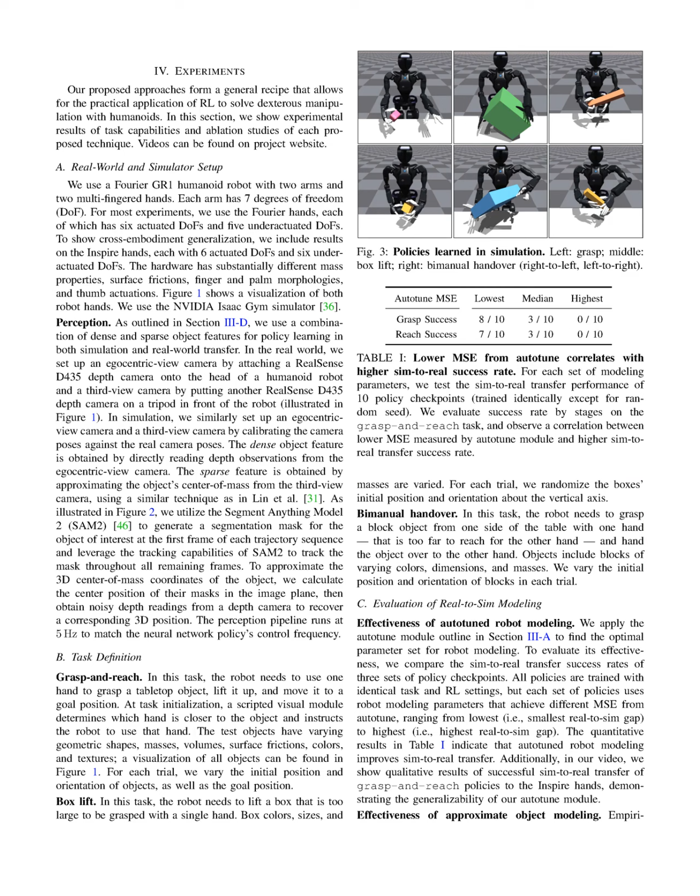Section Summary. In this section, we address the sim-to-real transfer challenges in vision-based dexterous manipulation by employing a combination of low-dimensional 3D object positions and high-dimensional depth images to balance information richness and transferability. We also utilize domain randomization and a structured perception pipeline with dual camera setups to enhance policy learning and validate our approaches through various manipulation tasks with a humanoid robot.